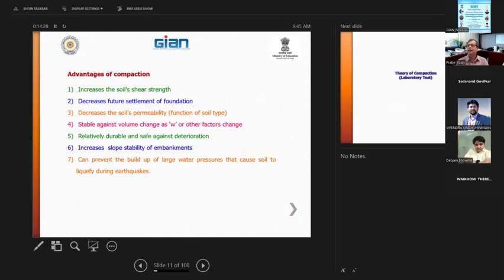Again, the shear strength parameters: tau is equal to C plus sigma tan phi, where C is the cohesion and phi is the angle of internal friction of the material. Most of the time, for coarse grain soil, the shear strength comes from this friction. How much is the angle of internal friction of the material? More friction means more strength. For clay type of soil, there is more stickiness or cohesion. There is an intrinsic cohesion. There are different types of cohesion.